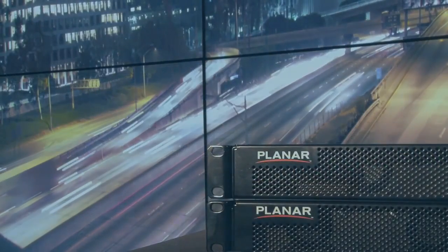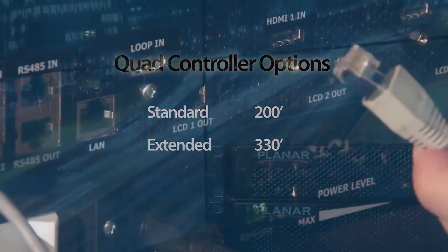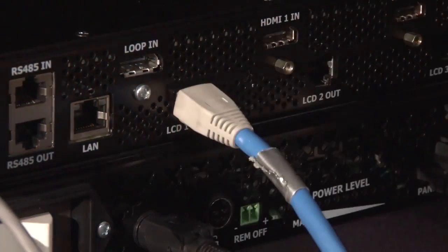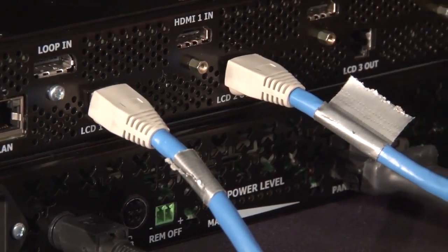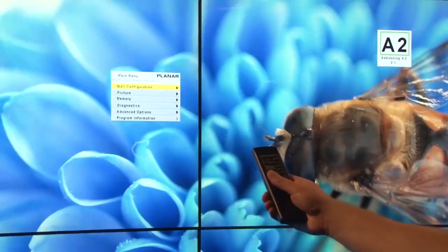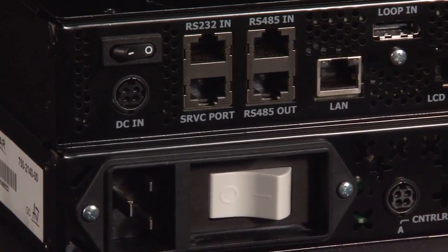2 different quad controller options are available. The standard distance quad controller allows you to send video signals up to 200 feet away from the displays. The extended distance quad controller allows you to send video signals up to 330 feet away from the displays, with no additional hardware required. To connect the quad controller, plug each of the Cat6 cables from the displays into the quad controller. The quad controller can be controlled with the IR remote, RS-232, or over a network using the optional integrated wallnet.